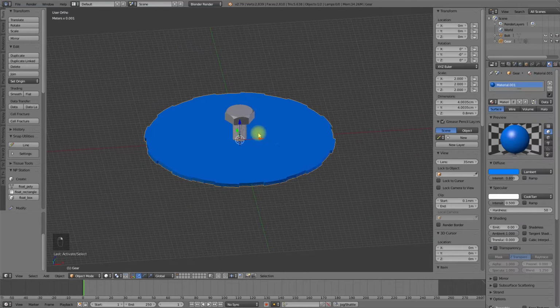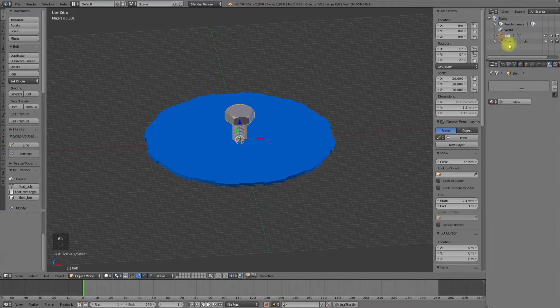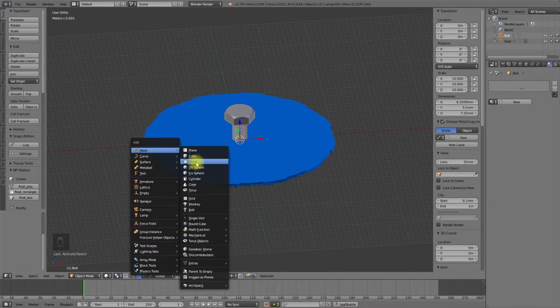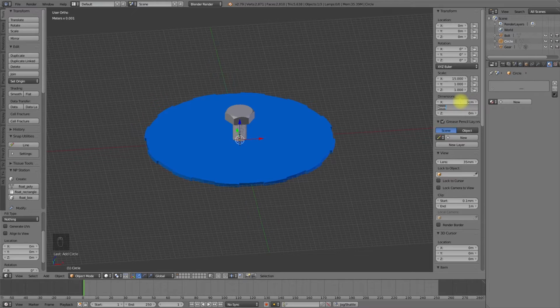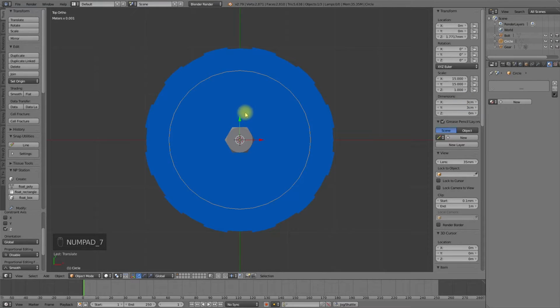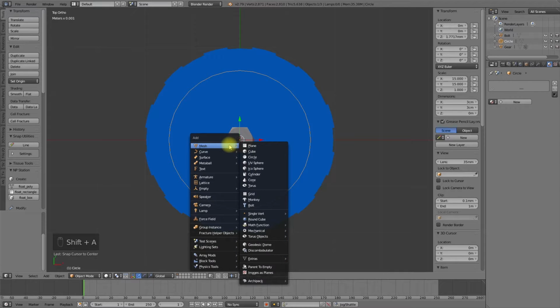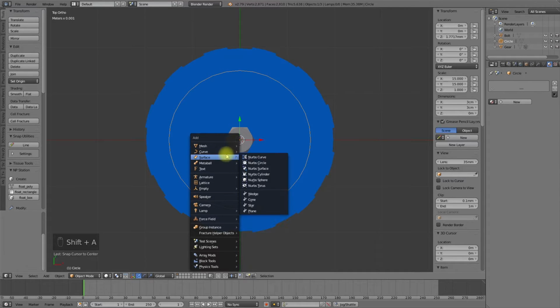In this example, I place a bolt object created with a bolt factory add-on onto a gear-like object. We want to position the holes for the bolts onto the path described by the circle points. Beside the bolt object, I need an object of type empty as the reference object for the array modifier. Therefore, I add the empty object to the 3D scene.